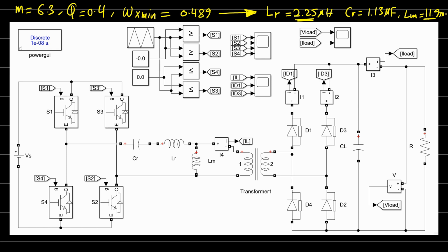We just need to specify the frequency. Make sure that you are operating at the right frequency. Of course, for the resonant converters, you will find that because of the relation between the resonant frequency and the components, there are standard values for the components, for the capacitors and inductors, and the resonant frequency is not always fixed. Like they're not always standard, right? If you pick a standard value for the capacitor and the inductor, you'll find that the resonant frequency is not a standard value. It's not 100 kilohertz or something. So you will find it difficult to exactly operate at the resonant frequency.